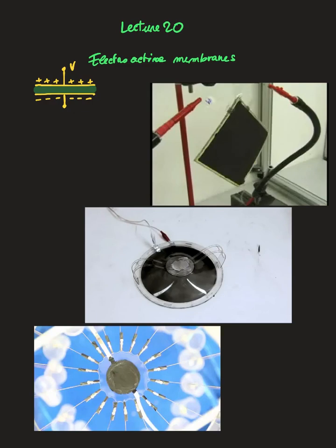like for example a silicone sheet or some insulating polymeric material, then the plus and minus charges compress it in the thickness direction. Since they compress this film in the thickness direction and it is incompressible, it has to expand in area.